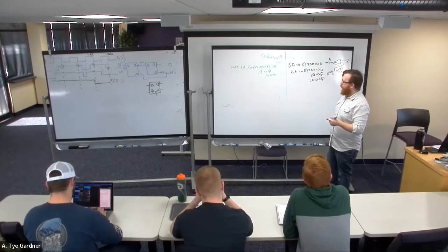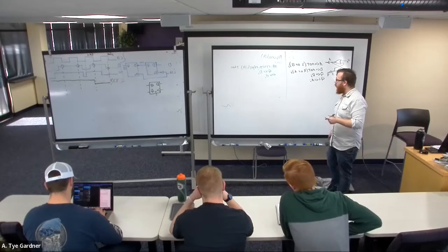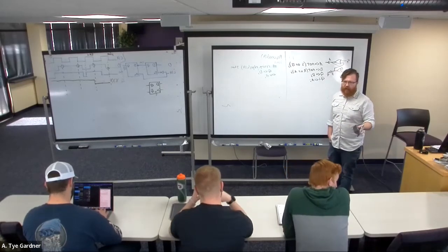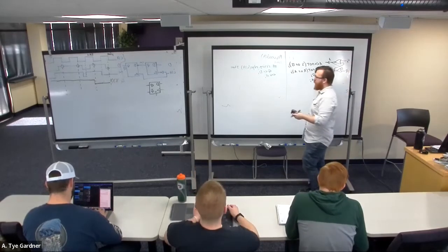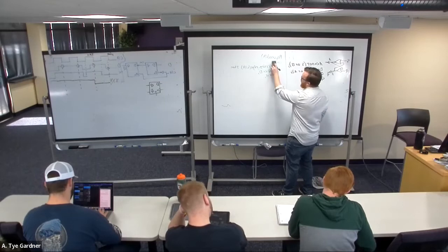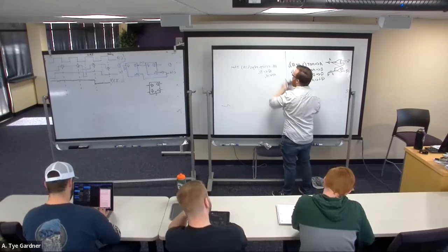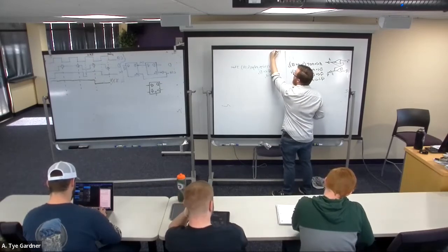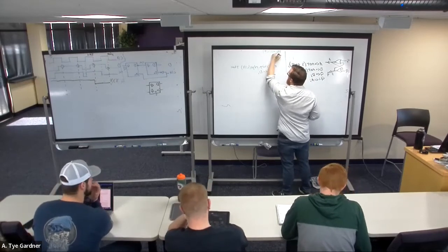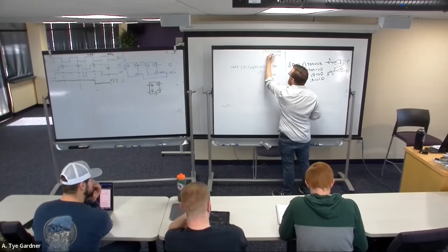So if I want to have a synchronous reset, meaning that it has to be synchronized to the clock in order to successfully reset, then all I have to do is modify this code just a little bit. I'm going to move the process up here. Process on clock. Begin.